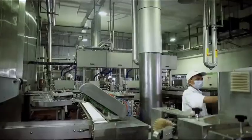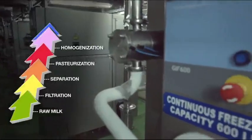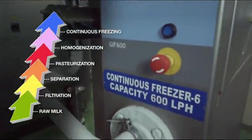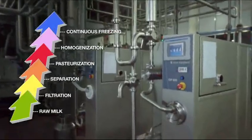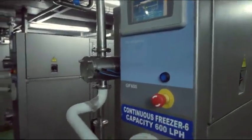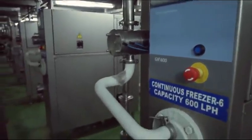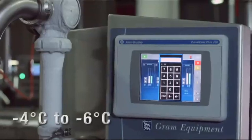Next, according to the formulation and recipe, colors, flavors and fruit pulps are added to the flavor mixing tanks called FMT. From FMT, the mix travels to the continuous freezing system. Here, water in the mix gets frozen and air is mixed into the emulsion with agitation. The amount of air added to the ice cream is called overrun. Overrun helps to make ice cream soft after freezing. The mix is transformed into a flowable mixture at -4 to -6 degrees centigrade.